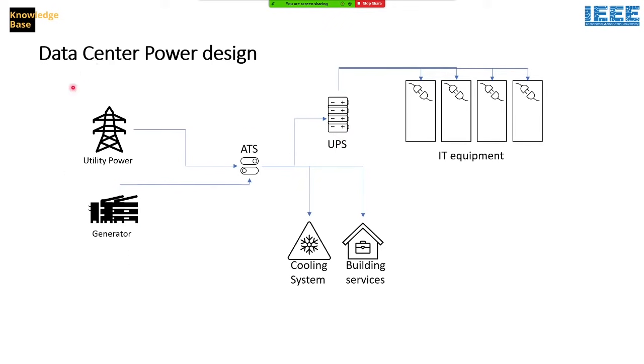Another thing, if you have a UPS for 30 minutes or 1 hour, it's useless because your cooling system is not running on your UPS. Your cooling system is running on the utility power. So if you're using a UPS and ignoring the generator, and you have 2 hours, after 30 minutes of the IT equipment operation, the heat inside the data center will go above 35 degrees, and by default the IT equipment will shut down, or you will have a fire or whatever.